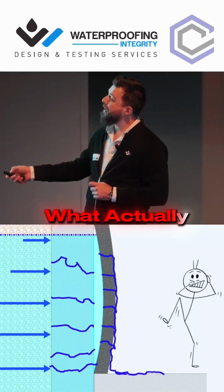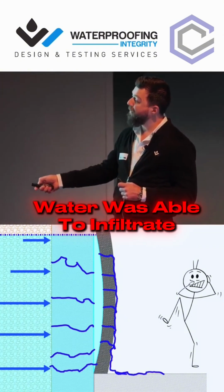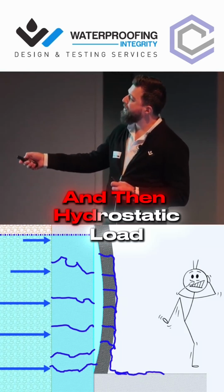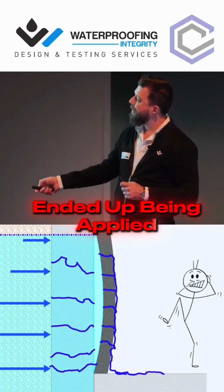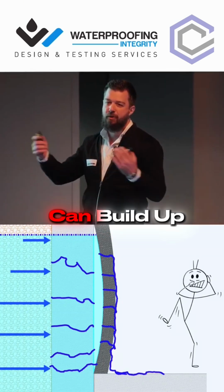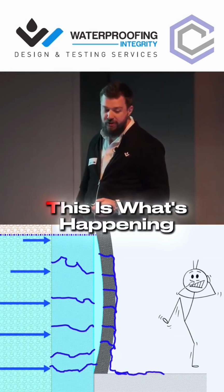So what actually ended up happening was water was able to infiltrate, very slowly actually, through this wall. And then hydrostatic load ended up being applied to our shotcrete surface here. And hydrostatic pressure can build up one drop at a time. But as it does build up, this is what's happening.